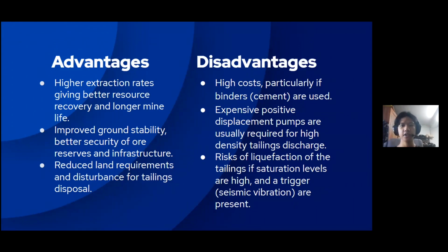The disadvantages are high costs, particularly if cement is used. If we add binders or cement, it makes this process very expensive. And if we are going to use backfill, we require positive displacement pumps for high density tailings discharge, and it's not cheap, it's expensive.